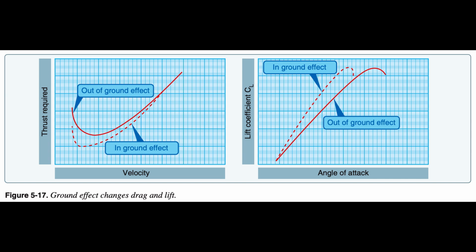Ground effect must be considered during takeoffs and landings. For example, if a pilot fails to understand the relationship between the aircraft and ground effect during takeoff, a hazardous situation is possible because the recommended takeoff speed may not be achieved. Due to the reduced drag and ground effect, the aircraft may seem capable of takeoff well below the recommended speed. As the aircraft rises out of ground effect with a deficiency of speed, the greater induced drag may result in marginal initial climb performance. In extreme conditions, such as high gross weight, high density altitude, and high temperature, a deficiency